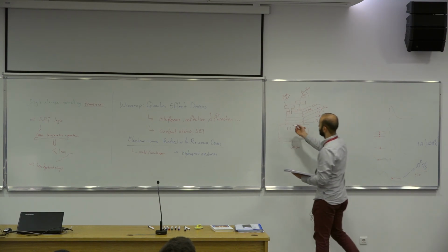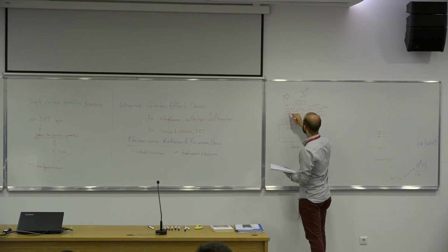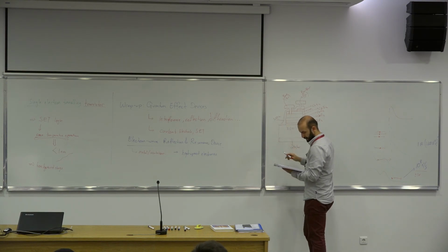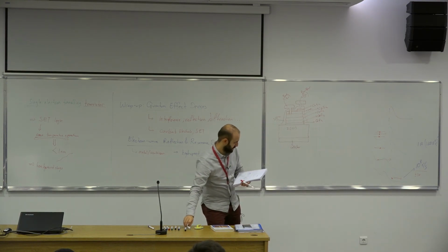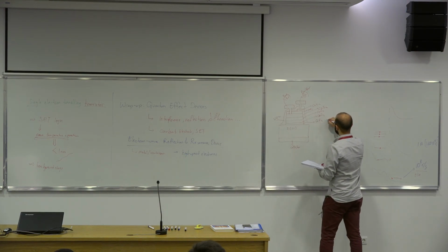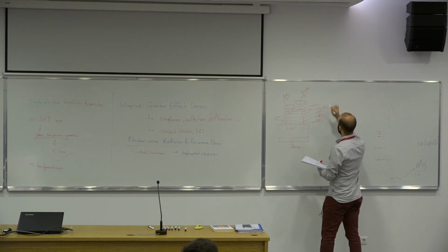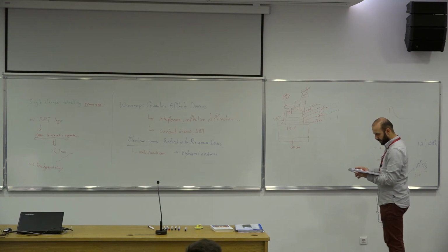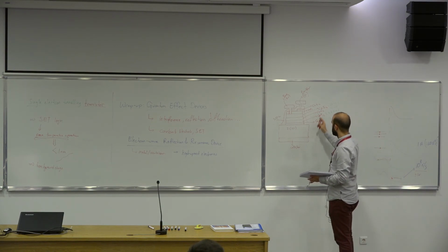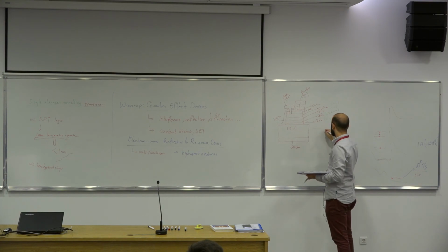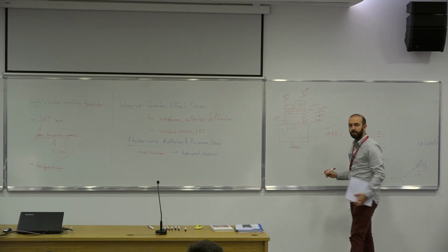And then there are some other details, like the whole structure is covered with silicon dioxide, and the layer thicknesses are, the first layer is like 0.9 nanometers, the second layer is like 2.2 nanometers, this is again 0.9 nanometers, this is 1.9 nanometers, and it goes on like that. The method to deposit these materials and the choice of materials actually are critical. They use molecular beam epitaxy.